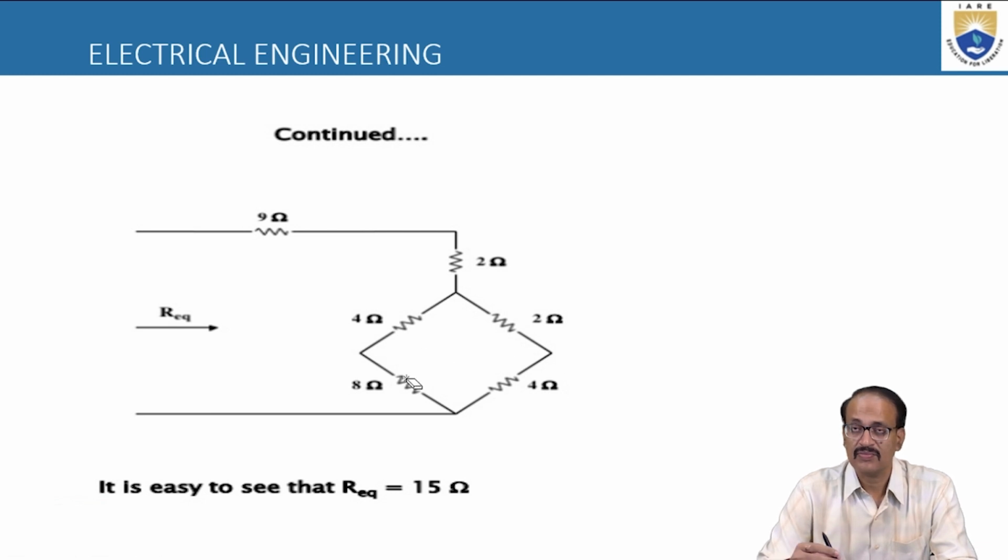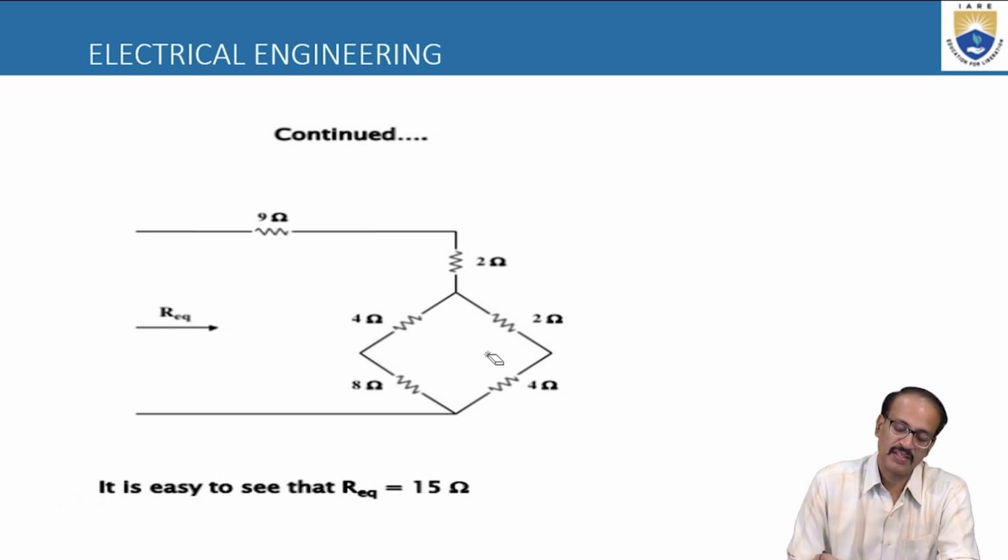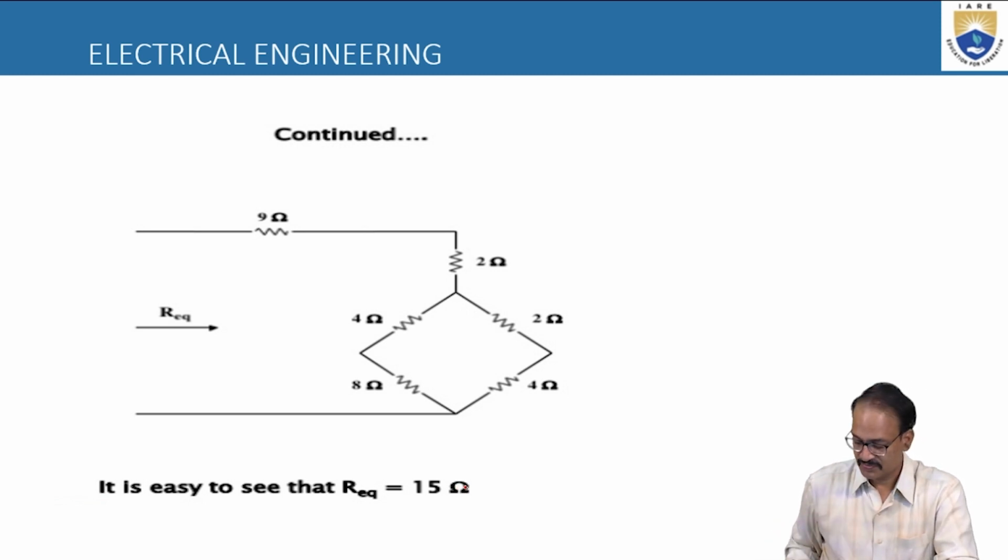After forming like this, we will simply add the resistors in series, and these two values we got, that is 8 into 12 by 12 into 8. The resultant value plus that will be 4 ohms. So finally this 9 plus 2, 11, plus the 4 ohms, and that will be 15 ohms.